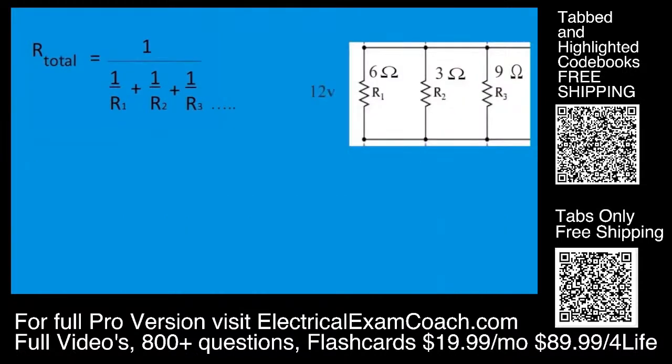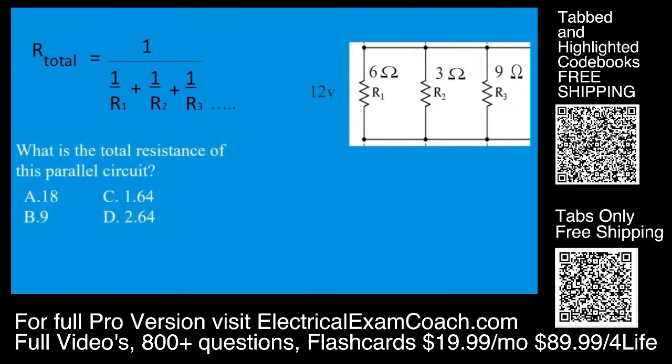Okay, so we have 6, 3, and 9 as our resistors. So what is the total resistance of this parallel circuit? I want to note right away that we have 4 options here in our question. The answer is always going to be smaller than the smallest resistor in the circuit. So if you're in your testing center and you get a question like this, we can tell right away that A and B are not going to be correct, because the total resistance of a parallel circuit is going to end up being smaller than the smallest resistor. That's an easy way to figure that out.